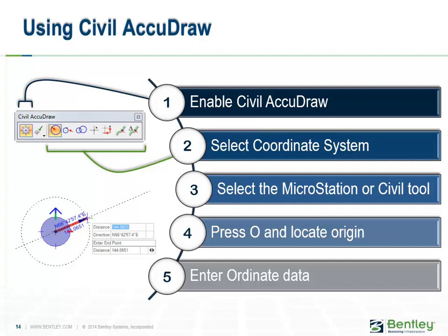Angles and directions are in degrees, minutes, and seconds format. They must be delimited by either a colon or a caret to designate degrees, single quote for minutes, and double quote for seconds.